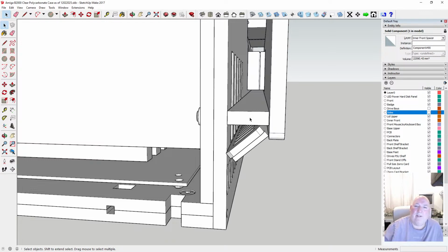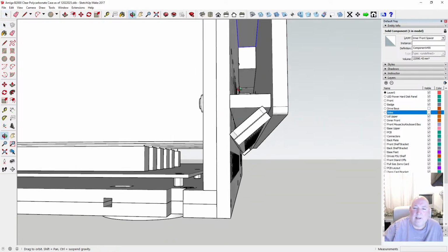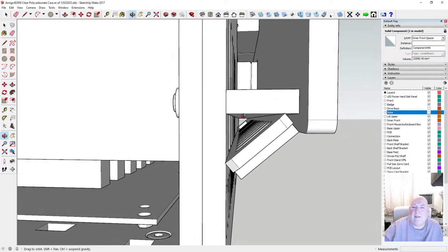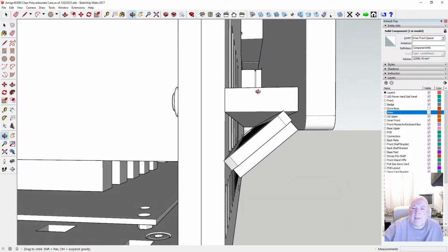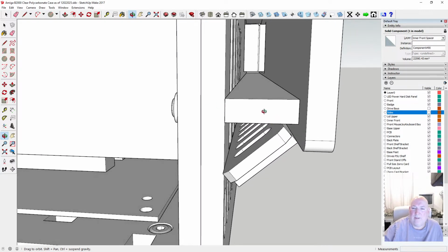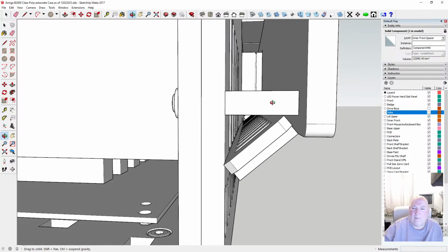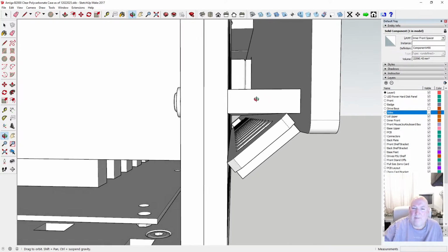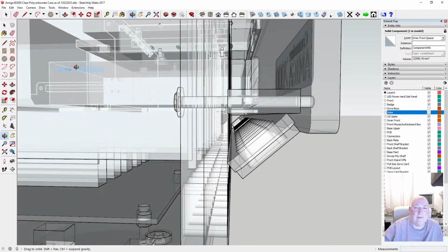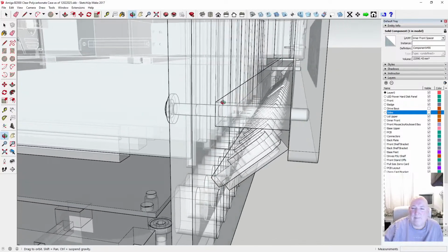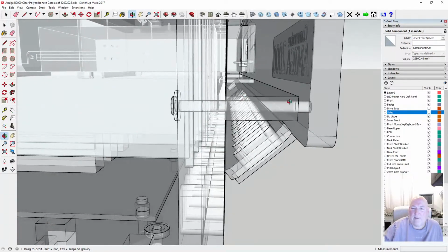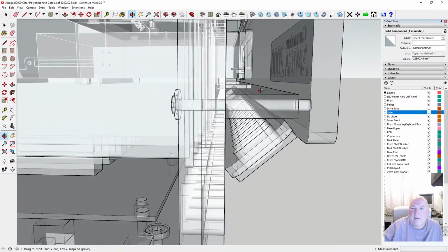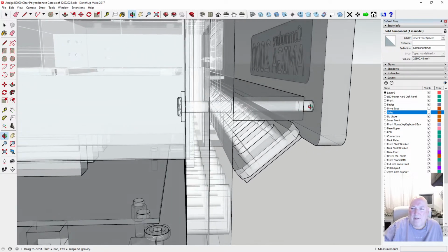Alternatively, what's another alternative? The other alternative is to mill out a pocket halfway, or just above halfway, and it literally sits on it. Just sits on the screws, and you tighten it up, but then there's nothing to stop it lifting up and wobbling. The screw needs to go through the centre, like that. Needs to go through to hold it still. And as you screw it, you won't be able to fasten it tight into the plastic here.